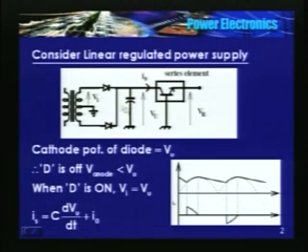Now the capacitor voltage cannot change instantaneously. The load current is also very small, or it depends on the load application or the time constant of the circuit. The capacitor voltage variation here depends on the time constant of the circuit. So this is the fashion. The capacitor voltage falls approximately linearly, changes not much. So till here, in the next cycle, the source does not supply any power. Diodes are reverse biased.